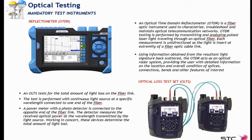An important point is that these two devices have to operate at the same wavelength. So whatever the wavelength you set on the transmitter, you have to set it in the receiver. Unlike what happens with the OTDRs, the OLTS is actually measuring. So the OLTS measurement is more accurate than the measurement estimated, calculated by the OTDR. But the OLTS does not measure distance. It only measures optical power.